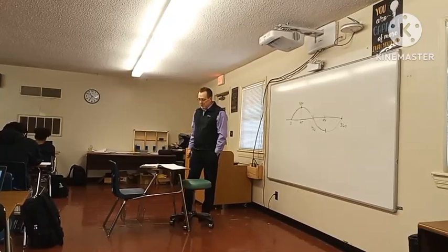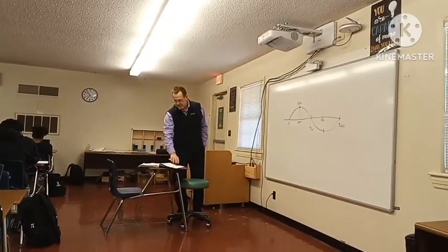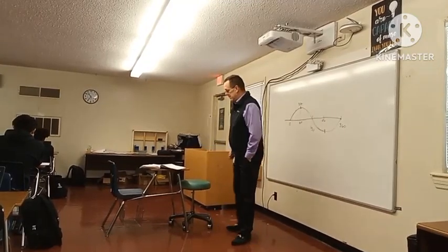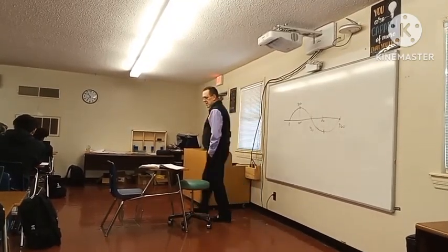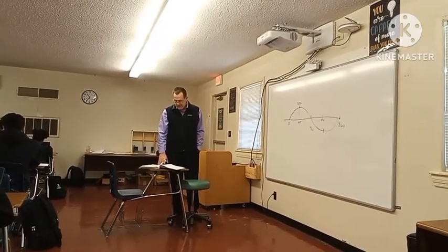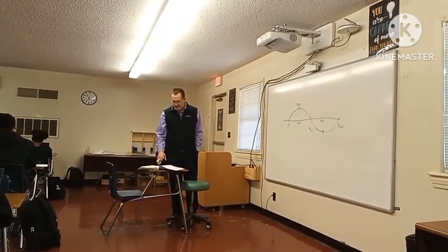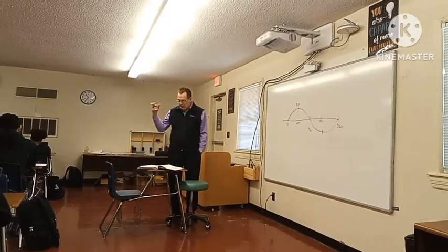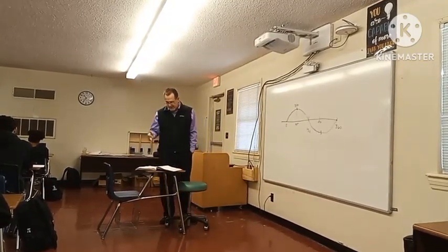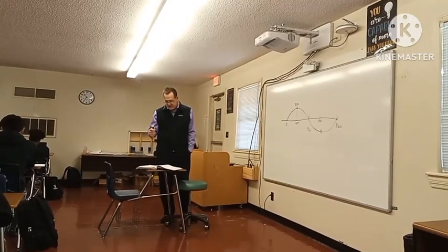Go to section 1.1.5. Average value. Miguel, what you got on that? The average value is calculated from all the values in the sine wave for one alternation or half cycle. Yeah. Half cycle is used for the average.